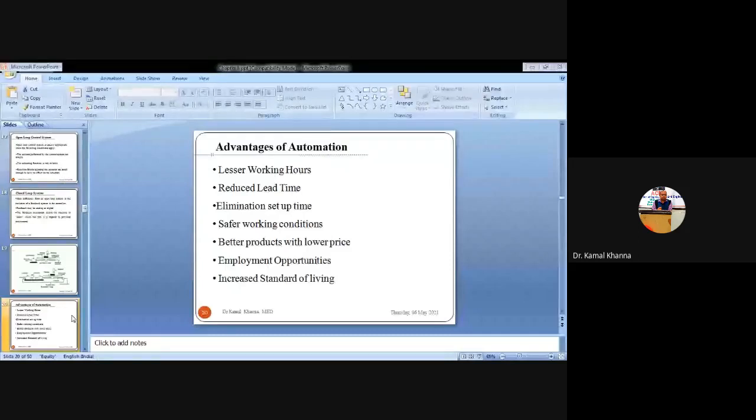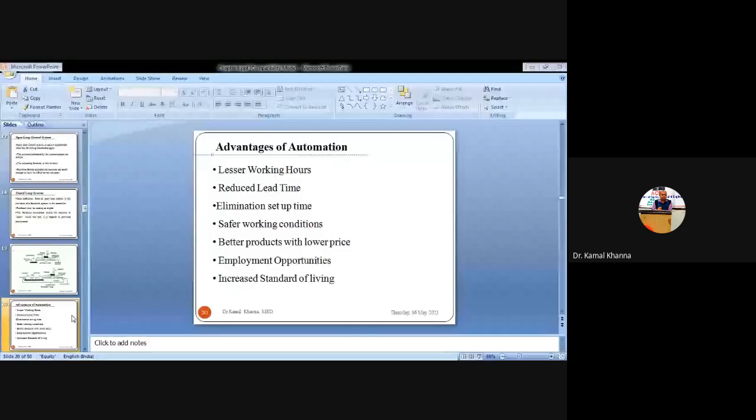We have also made available safer conditions to the workers who are operating the machines, because I showed you the pictorial view of the CNC machines in our first class, and that CNC machine is totally covered. There will be no chances of accidents that may have occurred in conventional machines. There is no flow of chips here and there. The chips and all the lubricating oil used in the cutting conditions are stored in the lower portion of the machine.